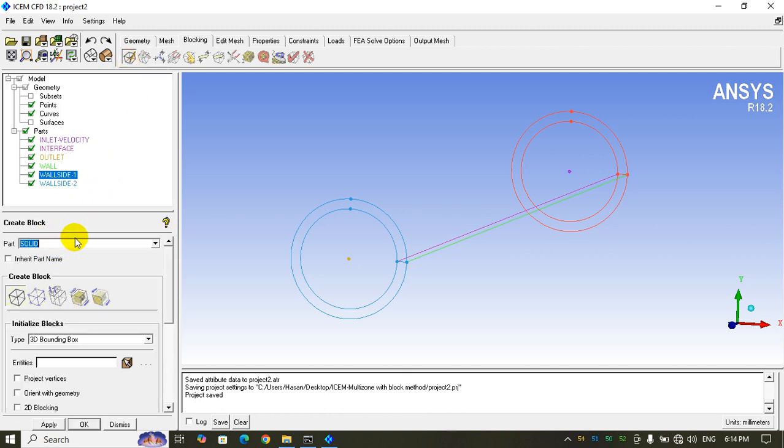Here you can name the zone. I mean, you can call it water or solid or tube or anything, but I want to name it as a zone. I suggest you do not use fluid and solid, because at the next step in Ansys Fluent, I want to create the coupled thermal interface automatically with the software.